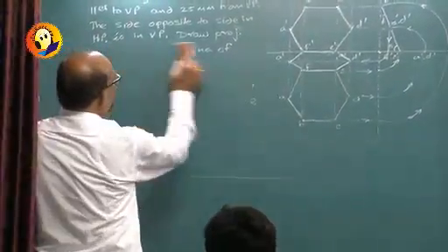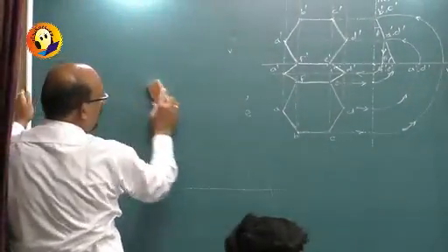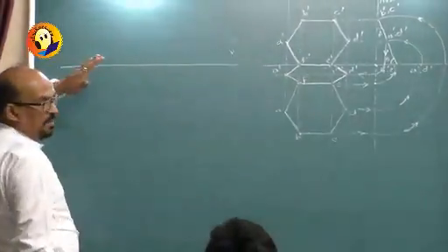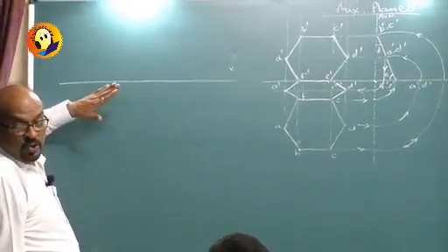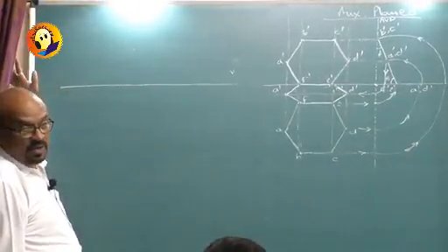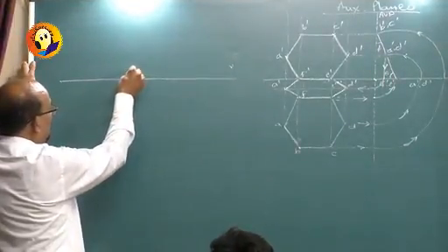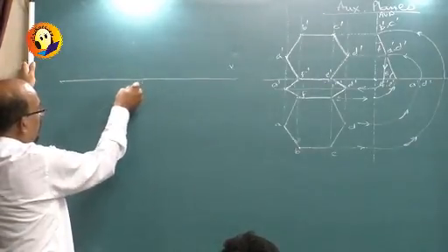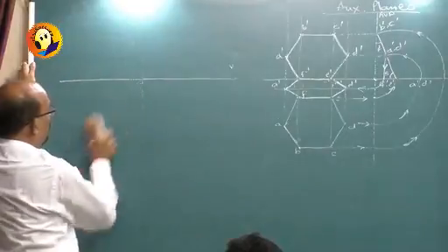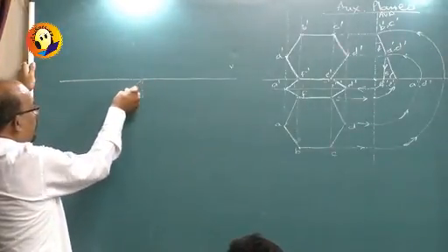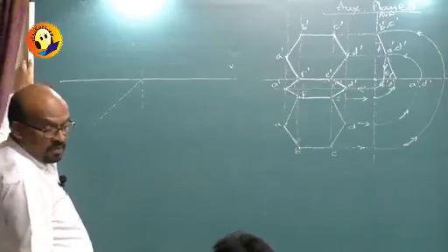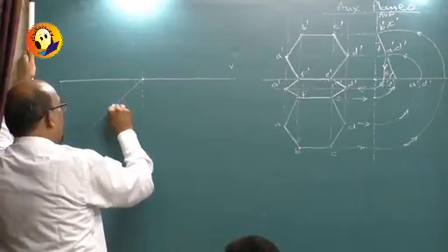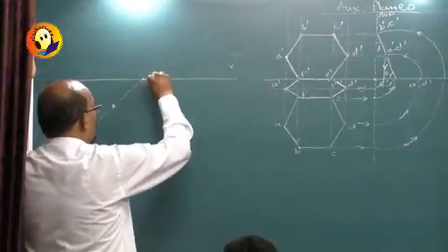In the second problem we have the pentagonal lamina, which is kept in HP, one edge is in HP and its corner should be in VP, and that edge makes 45 degrees. So we will have to start the problem by drawing a 45 degrees line. What was the side of that pentagon? 30. So we take one point here, measure 30 millimeters and draw the pentagon right over here.